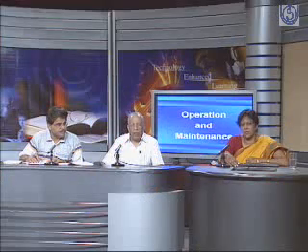Is it clear? Would you explain in a little more detail the reactive compensation? Why is it required? How does it help you? And in what form do you provide this reactive compensation? Okay, actually reactive compensation is required because you have inductive load on your system. Most of the loads on the system are inductive: the motors, the ACs, the compact lamps, CFLs, the fluorescent tubes, all these loads are inductive.